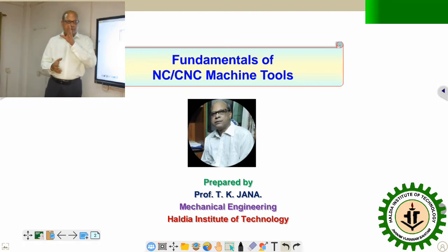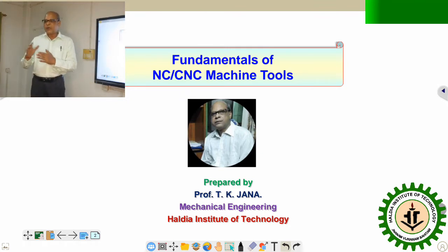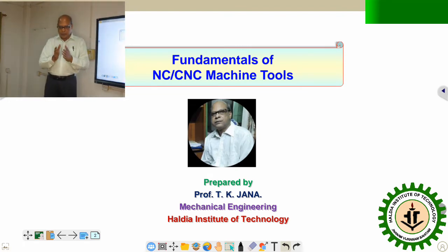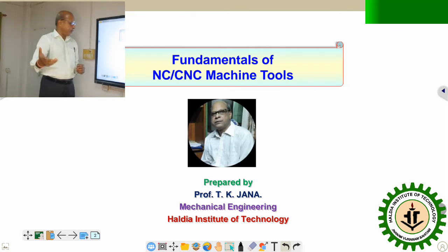And of course, the three major components of the NC machines: one is the program input device. The second, the heart or the brain of the machine, is the machine control unit. And third is the machine tool unit, which looks almost like our conventional machine tool, but with some modifications to the guideways, and a major modification in the replacement of the conventional lead screws by recirculating ball screws for improving the transmission efficiency. That link will be available in our next week.